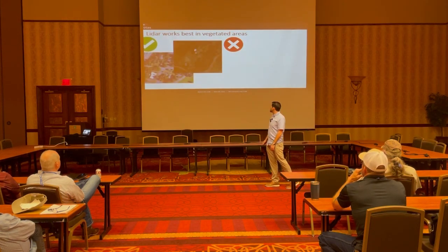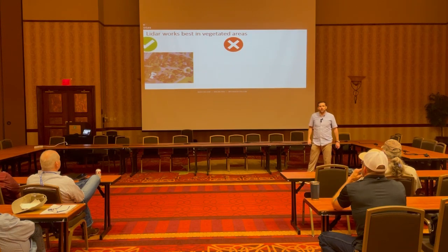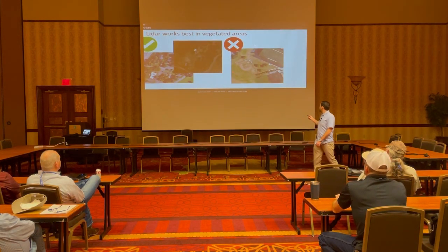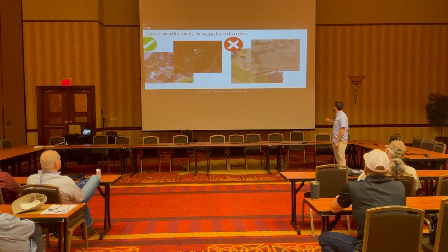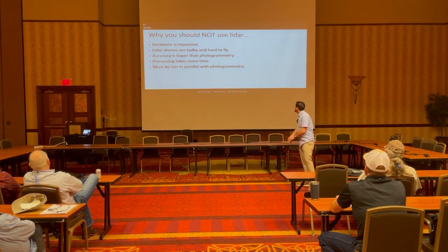Like I said, LiDAR works best in vegetated areas. If you do have very dense tree cover and you need topo, LiDAR works well. But if you're doing baseball fields, football fields, strip malls, dirt piles, stockpiles, anything like that, photogrammetry is going to typically be a better solution.